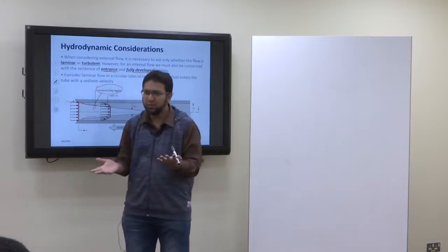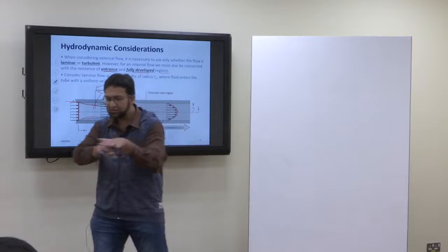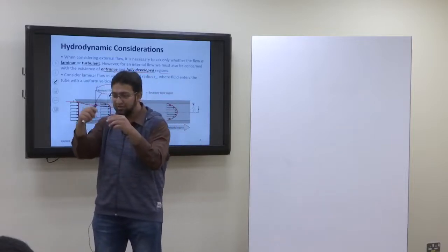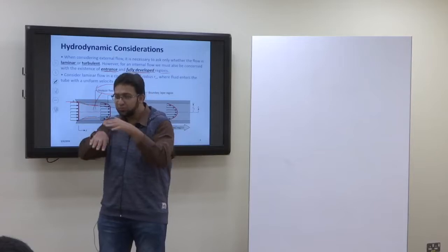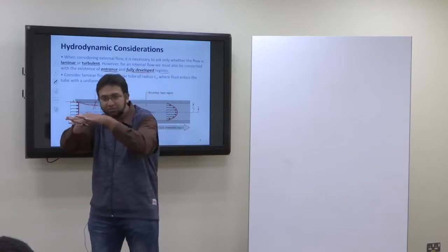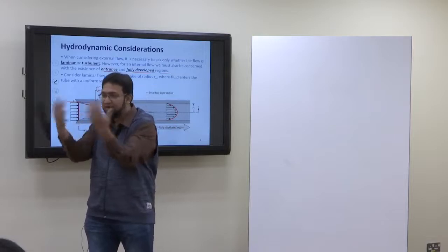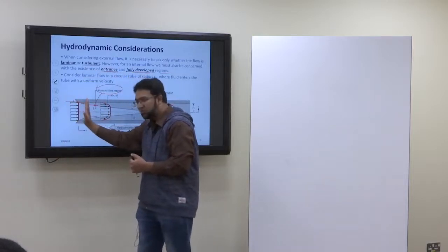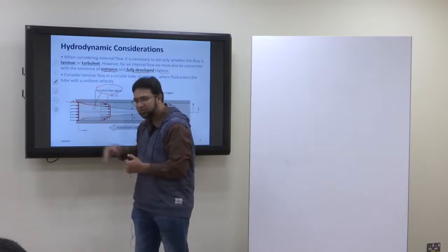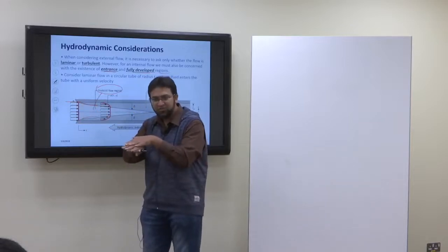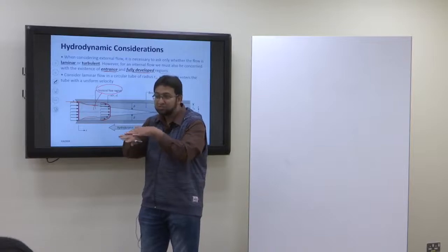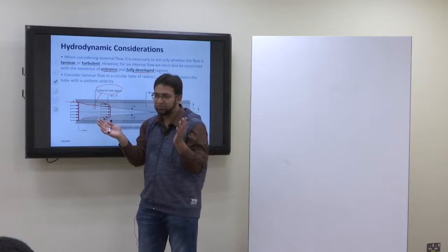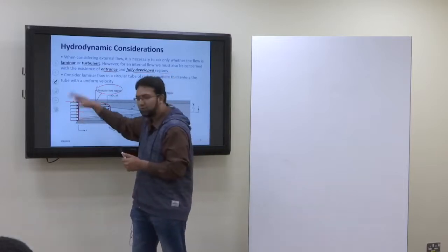Viscosity comes in effect when fluid flows in layers. Whenever there is a variation in the velocity of the fluid between layers, there will be friction between layers. So that's viscosity, right? So when the fluid is moving at the same speed, all the layers moving at the same speed, will there be any friction between layers? No. Friction is there when you have a relative motion. If there is no relative motion, no friction. So this is inviscid flow.